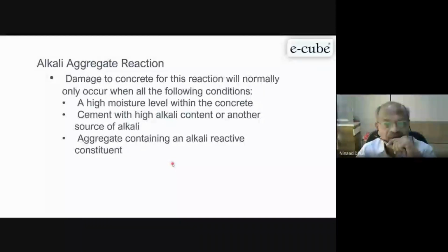But that is very important when you are working on a very big project like nuclear projects or dams. There we have to go for such a test because we cannot take a risk. Once you have constructed the structure, it's very difficult to repair it again, because these whole aggregates are throughout the body of concrete. As I said earlier, around 70-75% is only aggregates, and if those aggregates are reactive, definitely we'll have issues in concrete. So alkali aggregate reaction is also an issue in aggregate.